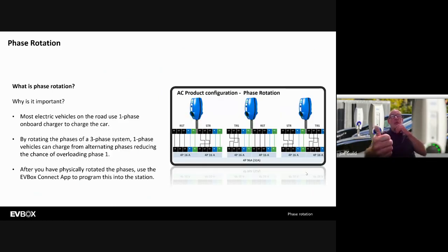We do that with a designation system. For you as installers, it's very simple: L1, L2, L3 in the first one, and then L2, L3, L1, and then L3, L1, L2, and then you alternate it. You can alternate it really 3 times. You can do it 6 times, but there's no effect. I've just found out that there's no effect for 6 times.